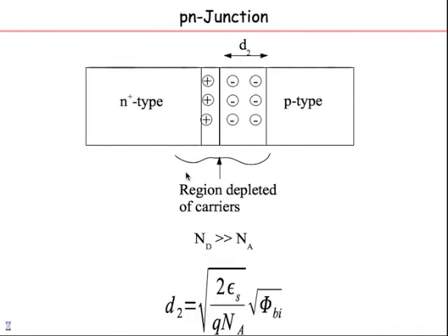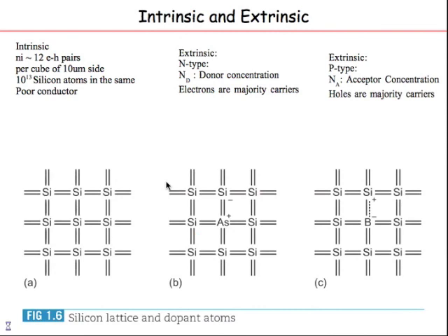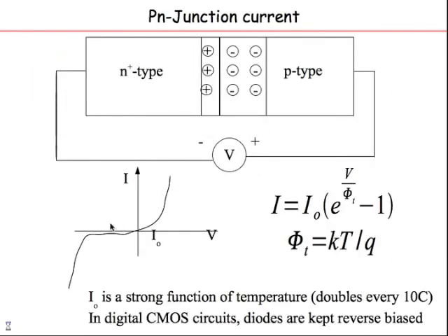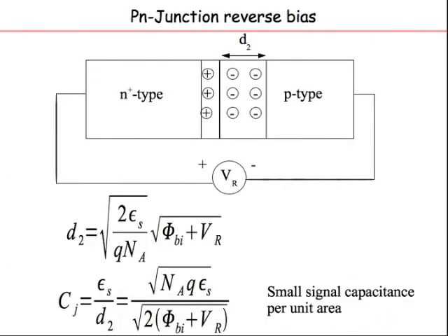And in the reverse bias, ideally there should be no current, but you end up with this current leakage. Essentially, it's a leakage current. So you have a diode which is reverse biased, but it's going to take up a small amount of current, and if you have too many diodes, it becomes a problem, right?